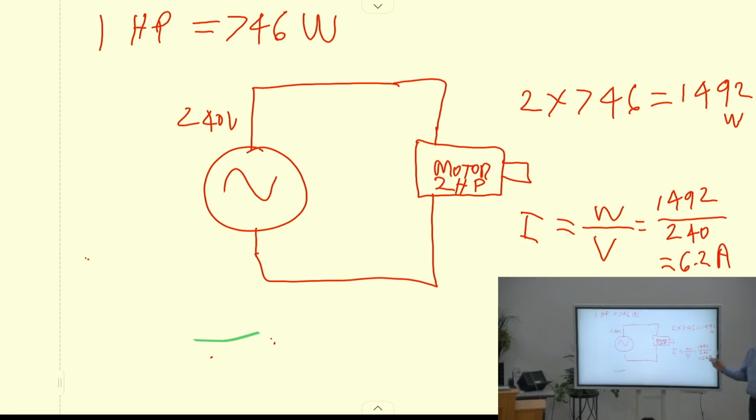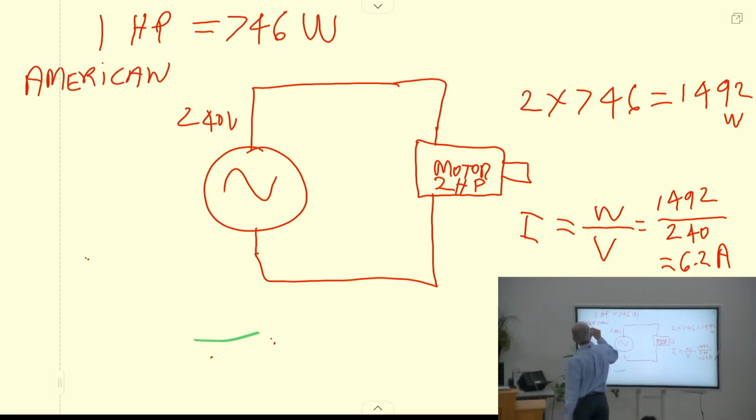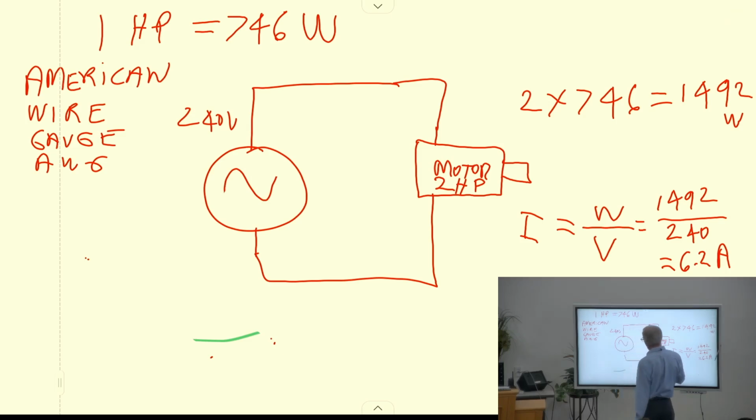Now, what size wire you need, the other thing you need to know is the wire table as far as conductors. What's the abbreviation that they always use in front of the numbers? Gauge, but what's the abbreviation? AWG, right? AWG means American Wire Gauge, known as AWG. We don't have all of these memorized. Good electricians have them all memorized.